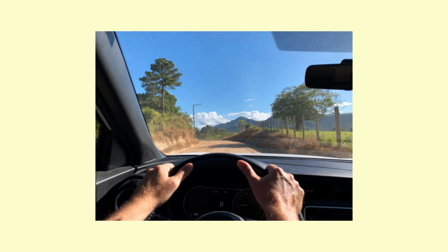The idea is to turn the steering wheel in the opposite direction of the corner for a moment, which shifts weight to the outside tyres. Then, quickly turn back in the direction of the corner, causing the rear end to swing out and help rotate the car.